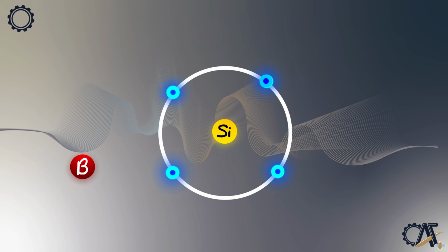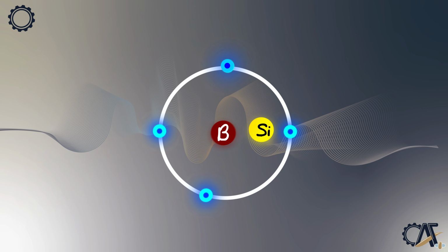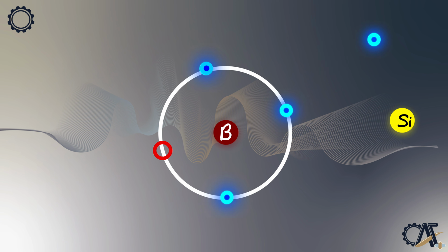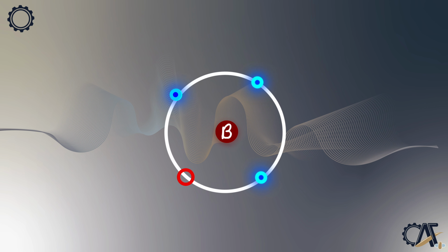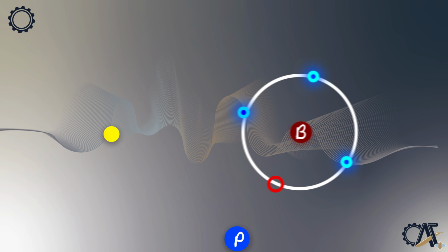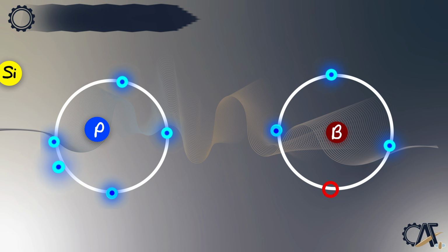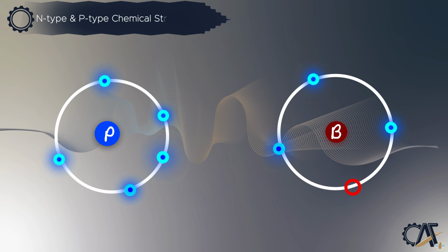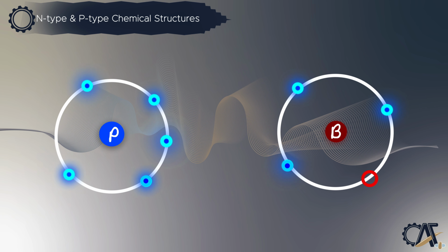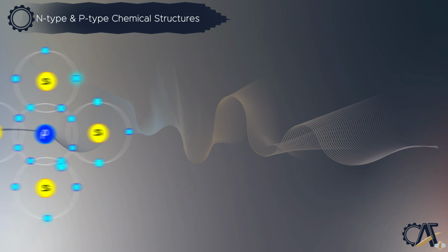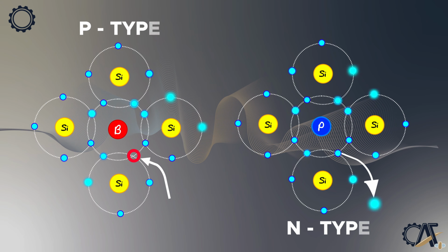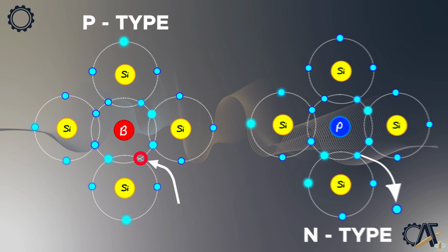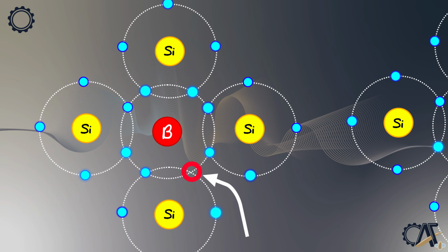If a semiconductor device is made of pure silicon, it won't present practical properties for making a semiconductor device. Thus, we need to build an extrinsic semiconductor. This type of semiconductor is the one in which a silicon atom is replaced with a specific impurity in order to improve the conducting properties. This makes the semiconductor suitable for electronic applications like diodes and transistors. For instance, when silicon is replaced with boron, it forms 3 covalent bonds in the silicon structure and leaves a hole leading to the formation of a p-type or positive semiconductor.